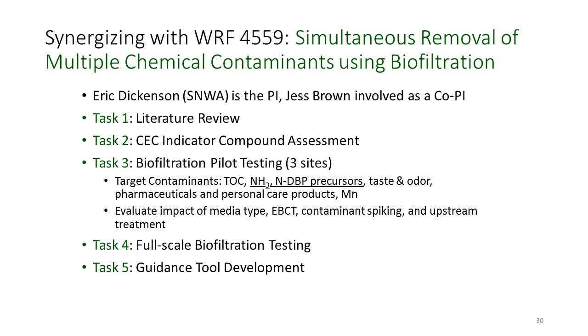There's been a lot of discussion about this over the years, and you've seen a little bit of that impact in the work Mihal just presented. Empty bed contact time is really the driver. Surface loading rate is really not the driver when it comes to biological treatment. The filtration aspect for sure, but not the biological degradation aspect. So we'll be looking at the impact of that.